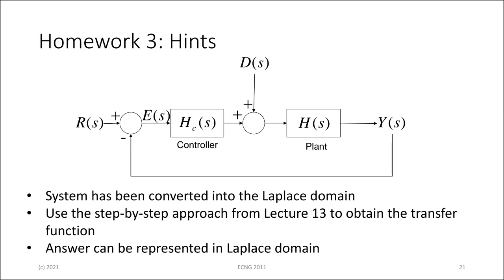You can swap the position of takeoff points together, and you can swap the positions of summing junctions together once they don't have a block or another takeoff point between them. All right? Once you remember the four basic rules, then you're all right.